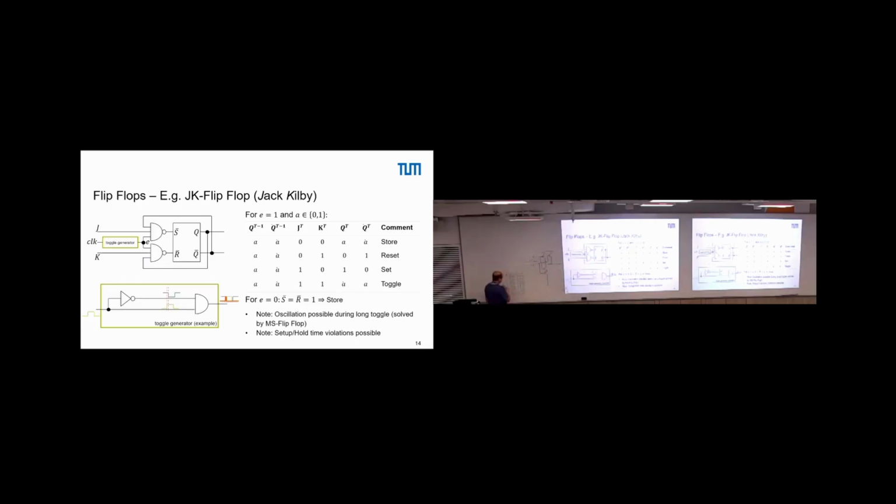We need at this point, we need to pull to VDD, right? Because we had here a 0, and now we want to have a 1, right? And then we are more or less done, okay? So, what we finally need is we add here another PMOS, connected to C. Now we have the effect that if here is a 0 and these two are 1, so for that case, we have a short circuit. So, we add another NMOS here, and now we are done.